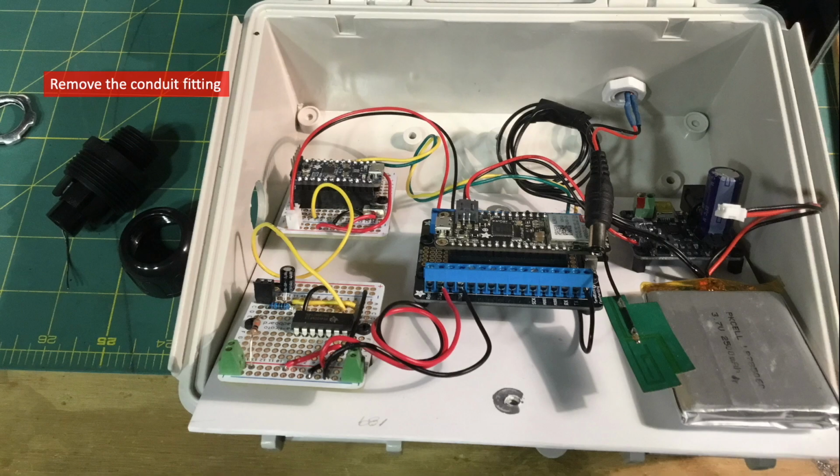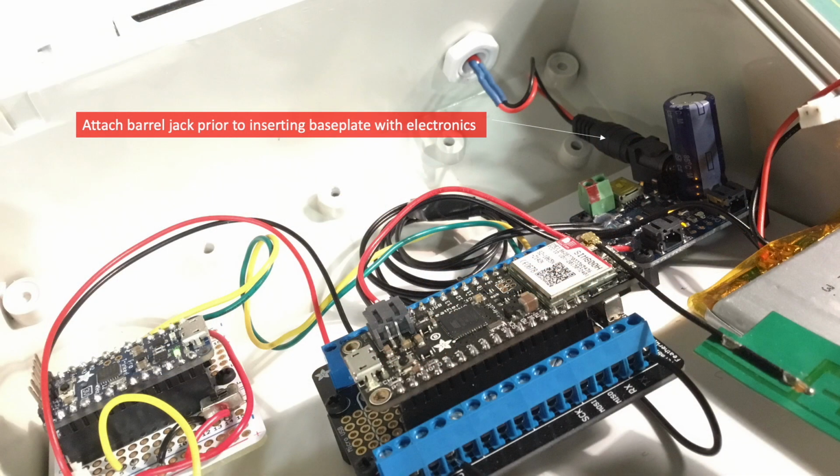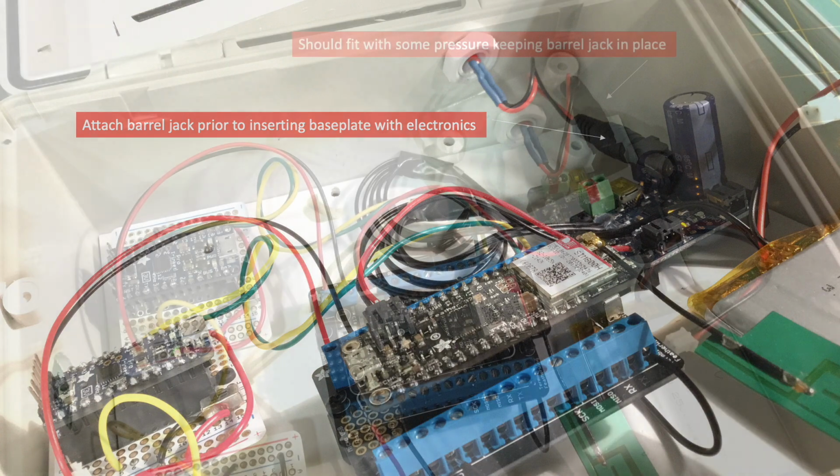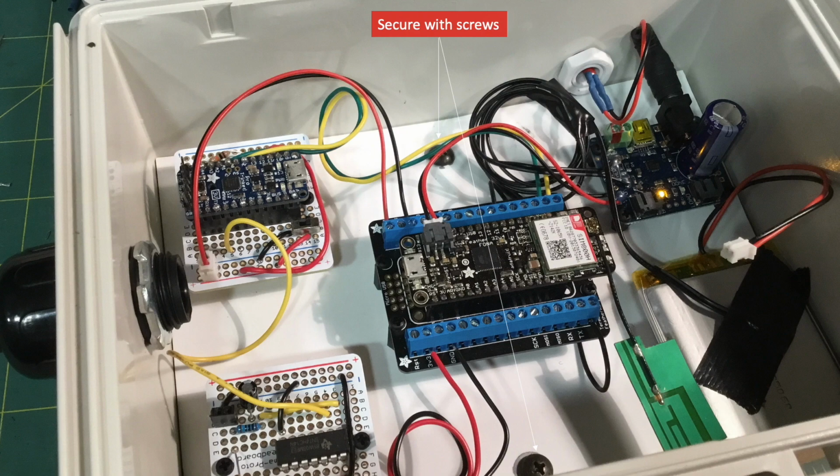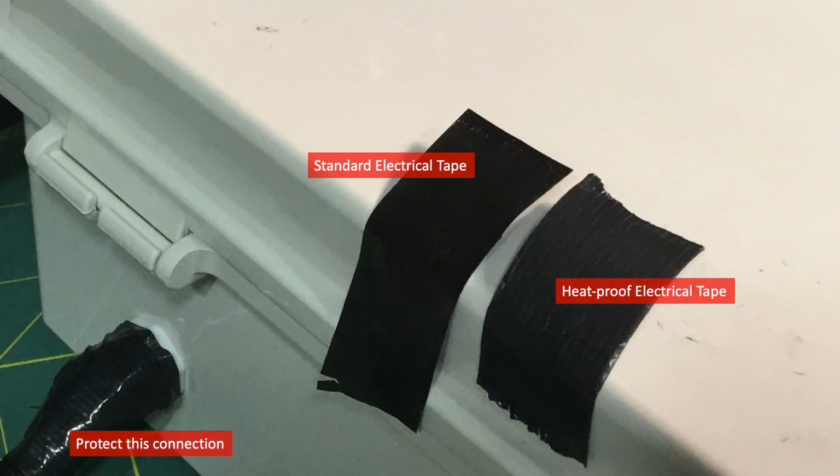Remove the conduit fitting from the bottom of the box and angle your base plate and circuit into the box. Before you flatten out that base plate in the box, attach the barrel jack to the solar LiPo charger since it will be difficult to attach the same once the base plate is fully inserted. The base plate should fit in the box with the barrel jack casing pushing against the wall of the box. This ensures it won't accidentally pull itself out should the box get jostled or the solar cable be pulled for some reason. Resecure the base plate with the screws and protect any exposed wire with some heat-proof electrical tape.